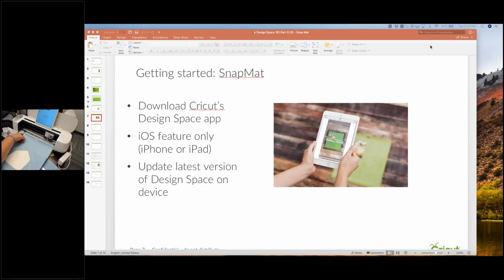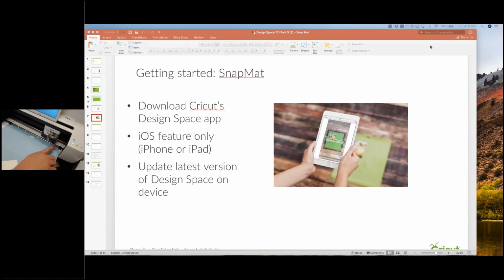These guides, the mat needs to be under the guides here, and have it as close as you can to the roller, because if there's a gap, when I click the load button, the roller starts to move and it's trying to grasp your mat. If there's air and space between there, there's nothing for it to grasp, and it might not load the way that it needs to be loaded. So just the tip of the day, have it underneath your guides, have it up against your rollers, and it also reminded me, have your pen loaded in clamp A.